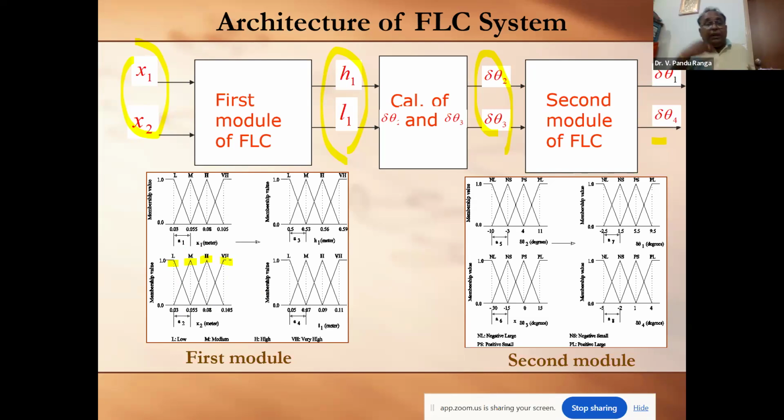While explaining the operation of a fuzzy logic controller, I said all the information will be processed in the form of fuzzified information. Even if you have a real number, that real number needs to be converted into a fuzzified form with the help of this membership function distribution and linguistic terms, and the data will be processed in fuzzified form. You will get a fuzzified output, which does not have meaningful information. That needs to be converted into a defuzzified output, a numerical value with certain magnitude that tells you how the control action will take place for the particular system.